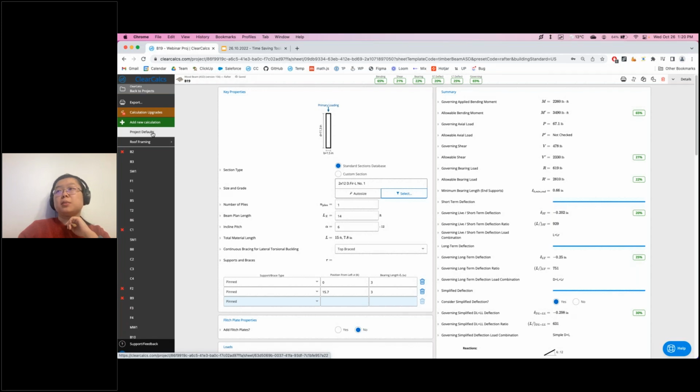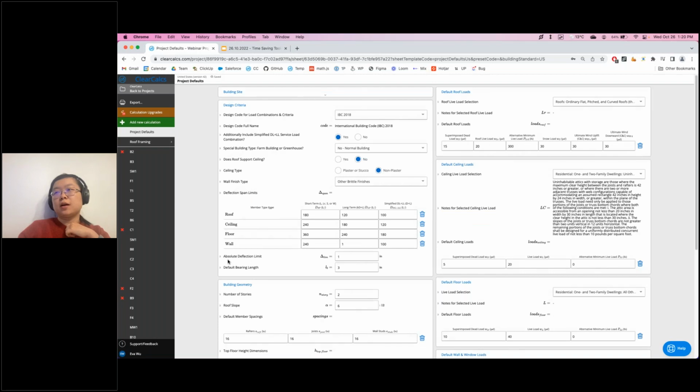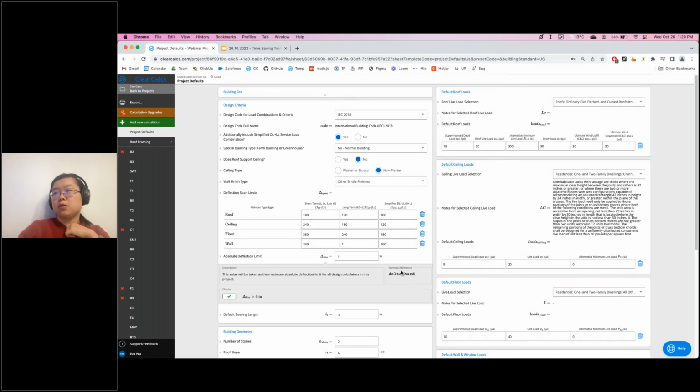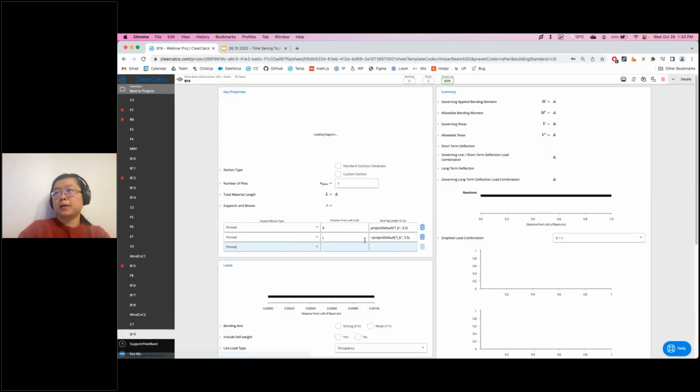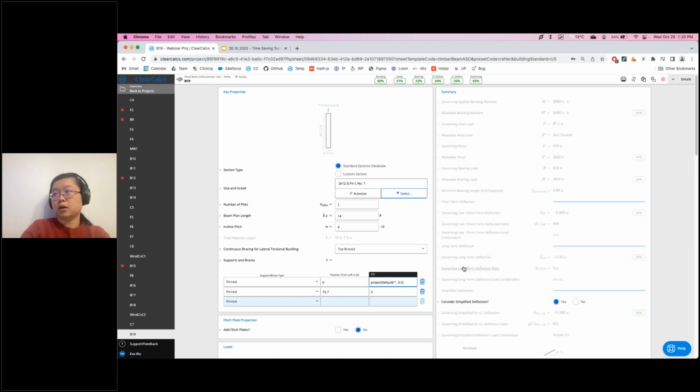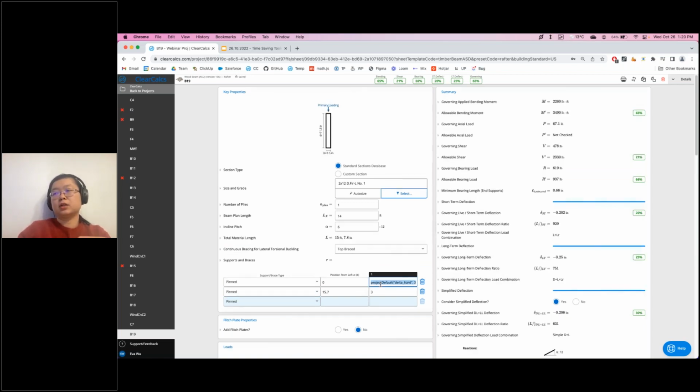Yes. But going back to the other question, if for some reason you wanted to set the absolute deflection limit as your default bearing length instead, if you pop this open, you can see it's called delta hard. So this really should exist for all of them. My apologies. We'll go back to the team and make those more readily available. But you can reference delta hard here and pop this open. And then instead of putting LB, paste in delta hard, and that will reference the 1 inch that we saw from the project defaults. The key here also is that the units have to match, or if the units don't match, Excel style math, which we'll get to, will have to be used to make the units match. Actually, that's a great point, and that brings us, I believe, to one of our other slides.